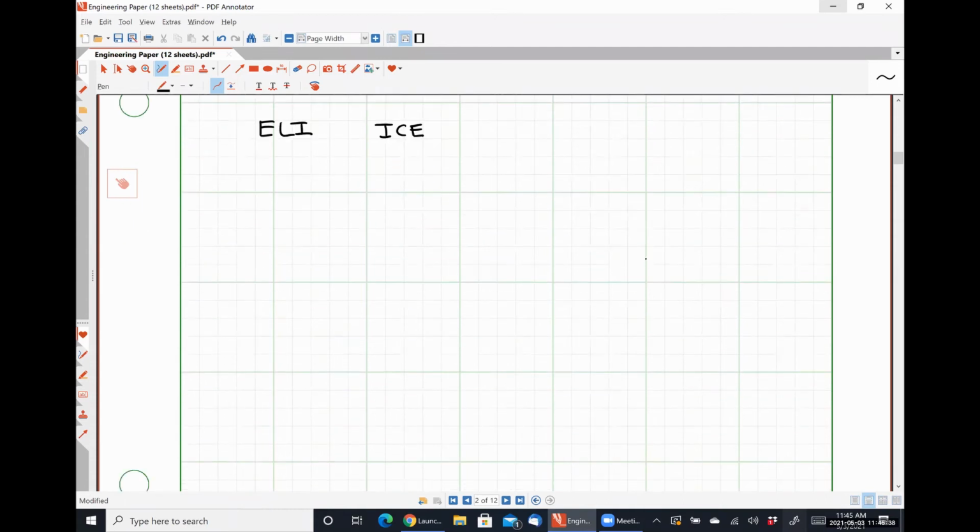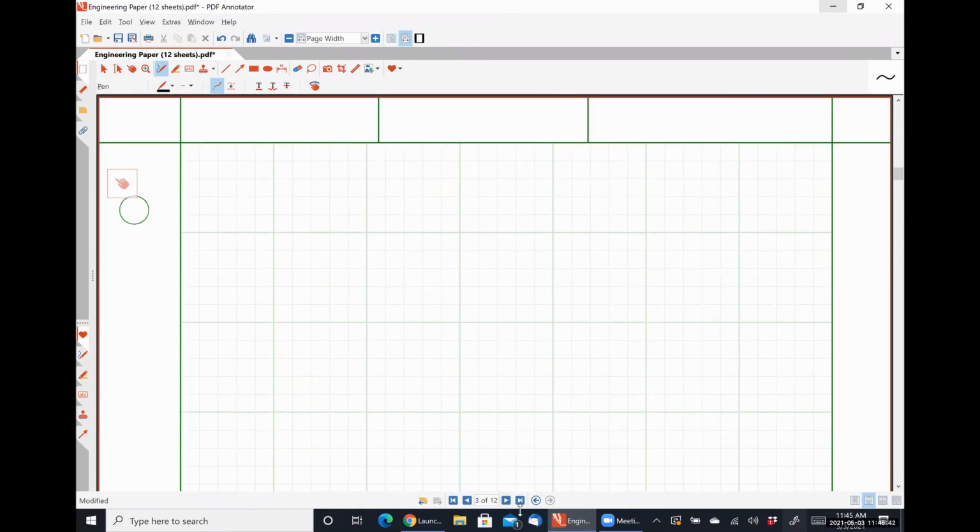All right, so let's now cover the power triangle. So in my opinion, this is where everything kind of starts to click, or at least I hope so. All right. So let's say that we have a generic load, Z is equal to R plus JX, where R is the resistance and X is the reactance, and we are assuming for now that both are positive quantities. A power triangle for this load would look something like this.